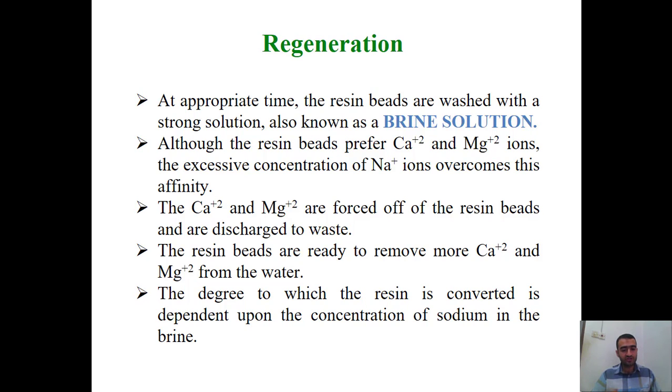The degree to which the resin is converted depends upon the concentration of sodium in the brine. So the more sodium in the brine solution, the regeneration solution, the washing solution, the more efficient the regeneration that will result.